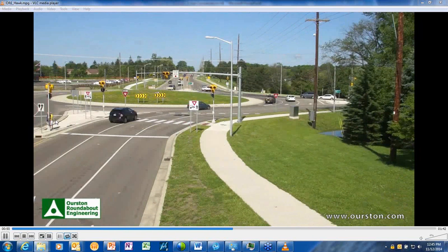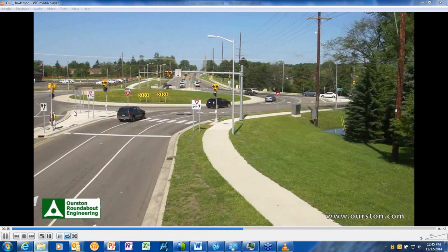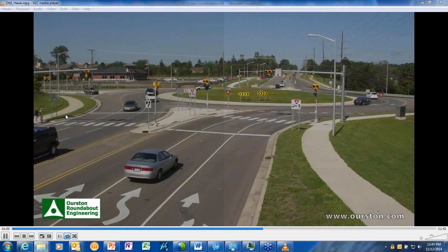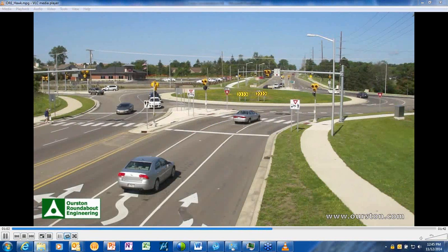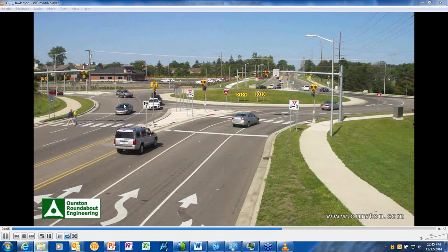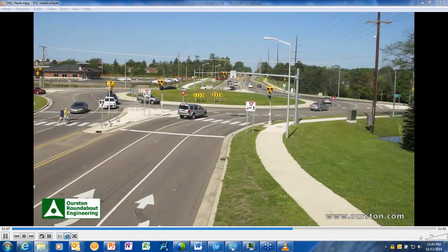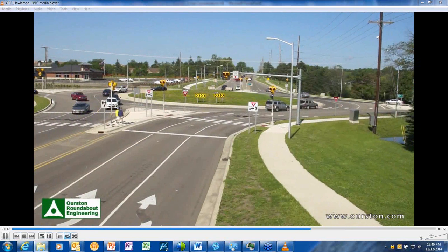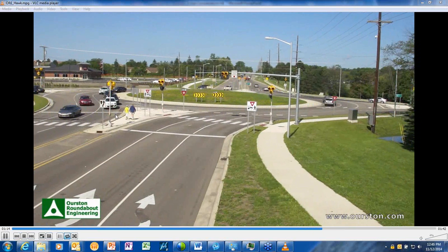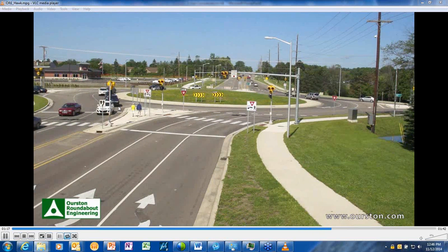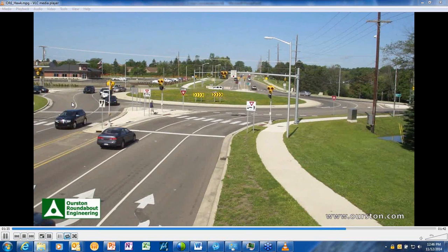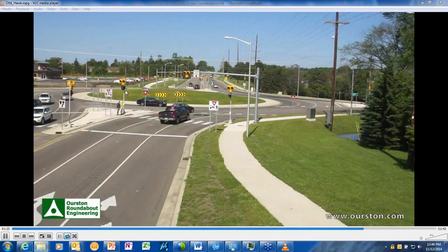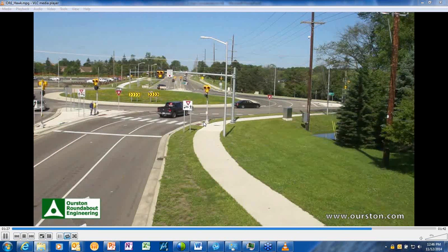So you see you need a few feet from the exit of the roundabout in order to place the crosswalk about 40 feet from the signal heads. Otherwise you don't have the cone of vision for a driver to be able to see the signal heads overhead. So we have to displace the exit crossing location just to accommodate those physical requirements. And the driver's got it here. It's probably in the flashing red mode, and there are countdown pedestrian signal heads on both sides. It can be made audible, so it's fully compliant with the Access Board.